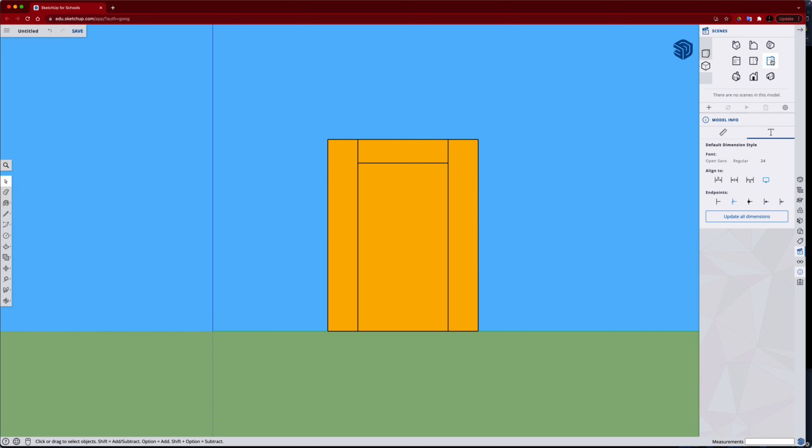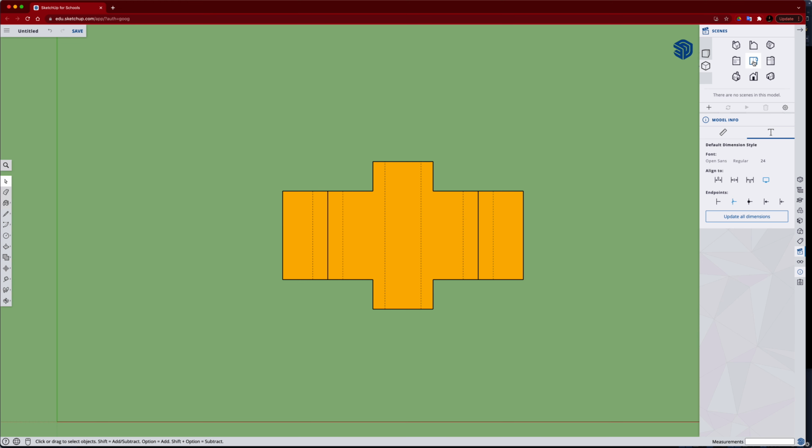And over here will be my right side view, and all these lines that we see are the object lines, but if I want to see any of the hidden lines, I just press the K button, and that will display the object lines and the hidden lines. And you can see in the top view that there are also some object lines and hidden lines that we're going to need to draw.